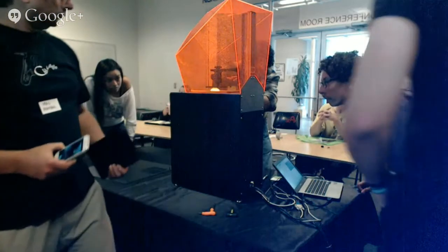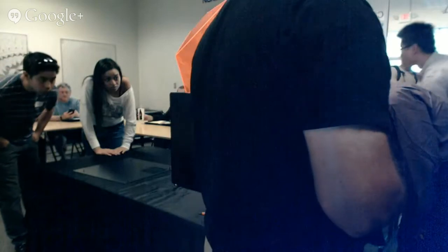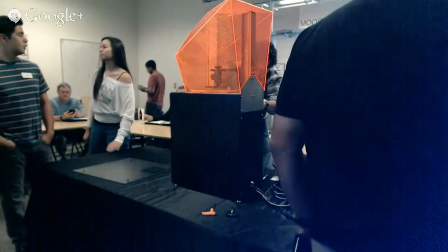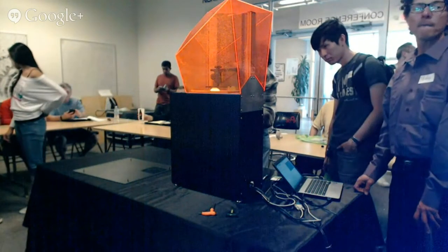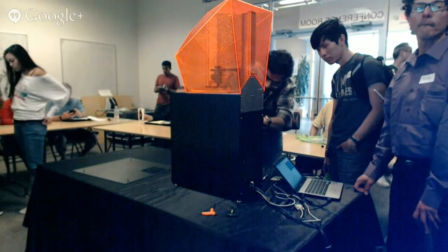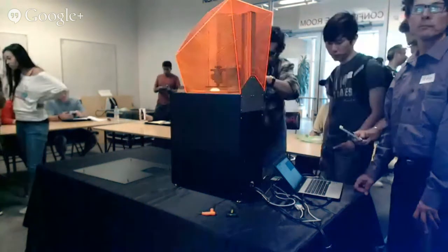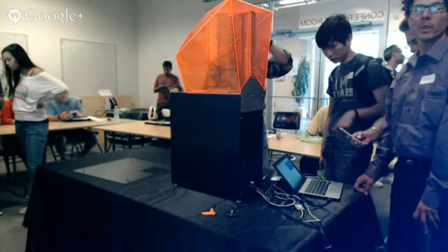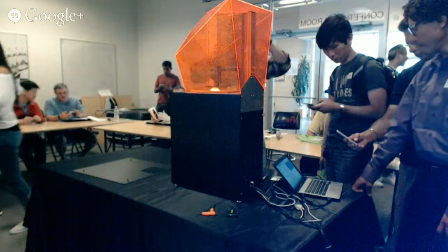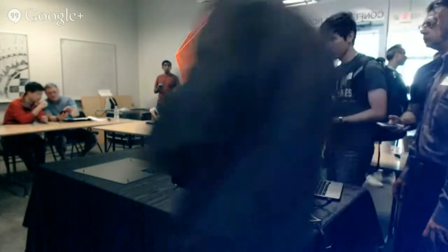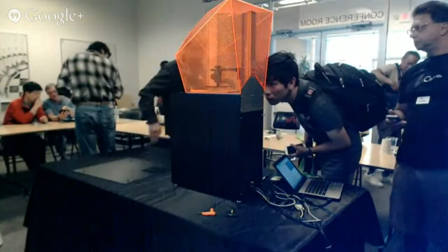When you say burn out, it doesn't mean that you light it on fire. You have to have a special kind of kiln for it, right? So this is for professionals, because you have a special kind of kiln that has good temperature control, so you can cleanly burn out the material. But what you do is you put plaster or whatever around the part, then you burn out the part, and then you pour the metal in, and then you break the plaster, and then you have the part. It's one-time use for heavier metal.